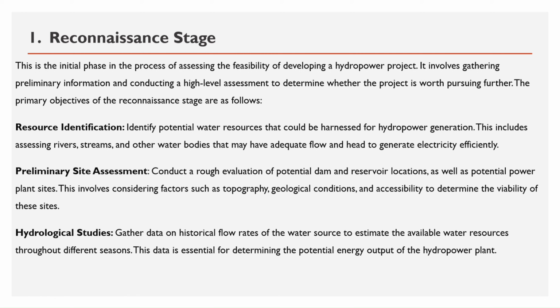Hydrological studies. Gather data on historical flow rates of the water source to estimate the available water resources throughout different seasons. This data is essential for determining the potential energy output of the hydropower plant.